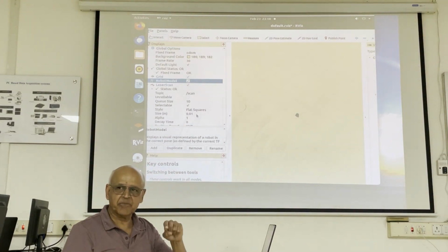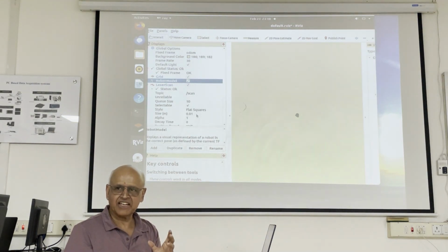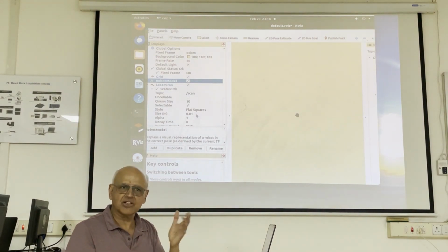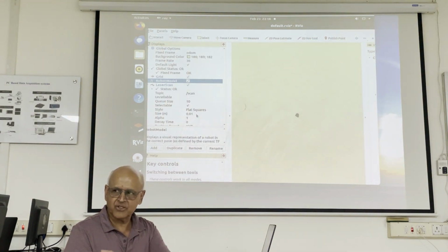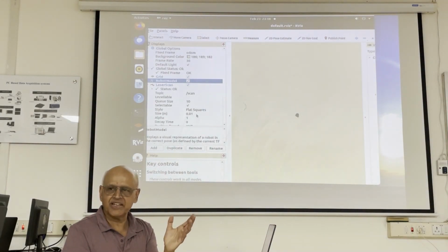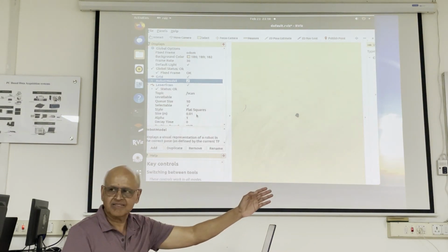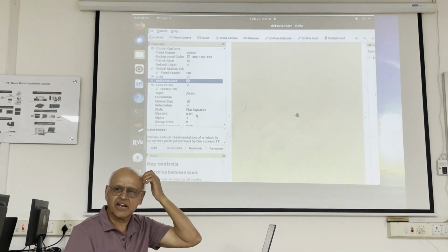So this is subscribing to the same topic. It's not a different topic. The LiDAR scan is called /scan, the topic, and RViz is also forced to subscribe to it. Do you get it? Do you get the structure of ROS? From MATLAB, you can subscribe to the same topic. Everybody can subscribe to it, anybody who's interested. It's like a bulletin board, right? Anybody who goes by the bulletin board can look at it.